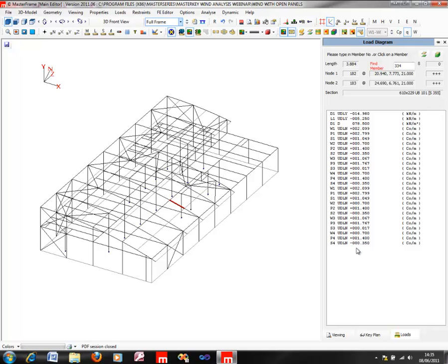The reason these are given like this is because the actual Q value can vary from one wind loading case to the next because of wind diagonals. So if we were to list all the values for all the different cases, you would end up with quite a range of values. Those are multiplied at analysis time by their appropriate Q values, dynamic site pressure values, and any other factors that might need to be employed there. So just to bring that to your attention.